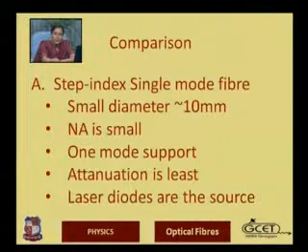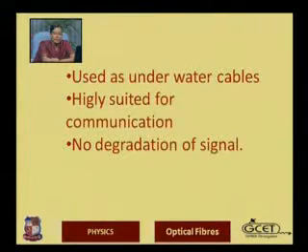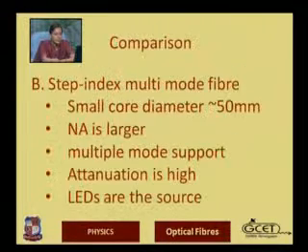Laser diodes are the source. Laser diodes can be used as the source for this type of step index single mode fiber. It is used as underwater cables. It is highly suited for communication because of least attenuation and no degradation of the signal.